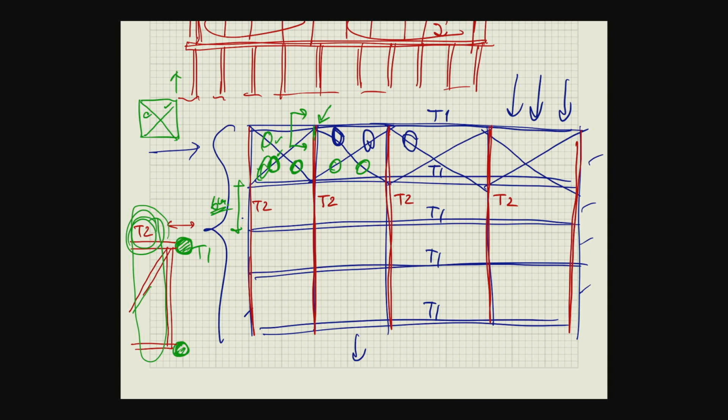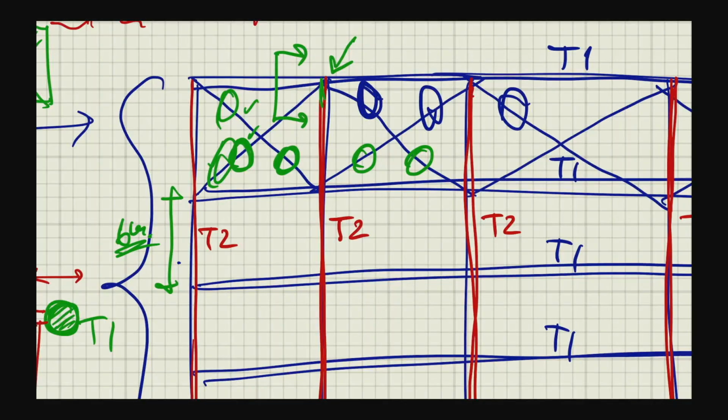All right. So when you design, you just imagine that you have just one piece, and that one piece has to carry the whole force, and that will be under the tension mode only. In the reverse direction, that tension is turning into compression, and then it does not contribute anymore. So the force is handed over to another one. But the thing is that the bracing force we need in here.